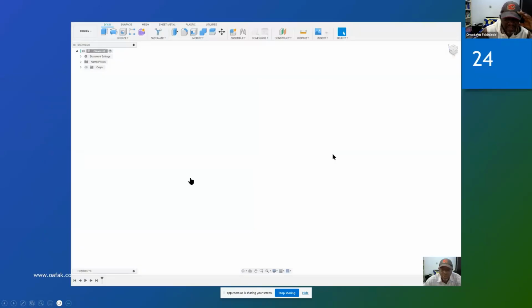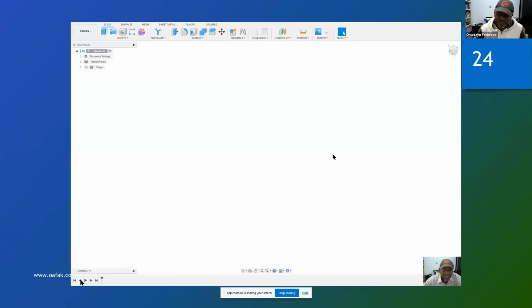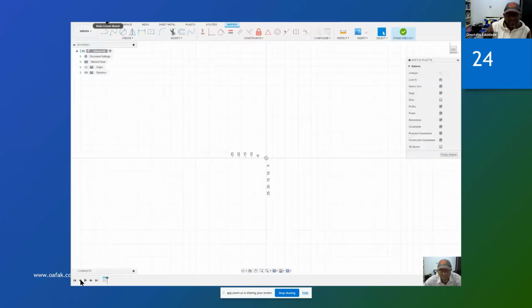The same thing is in this clip. So what I've just described is in the clip here. To do that, you start by creating a sketch, and then you do a circle, as I said. And after that circle, you draw a line inclined. So you are going to draw another line from the center up.